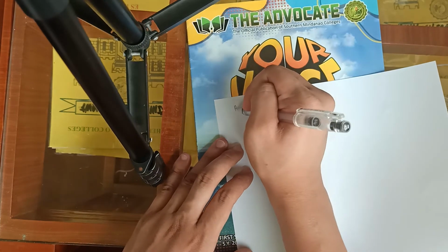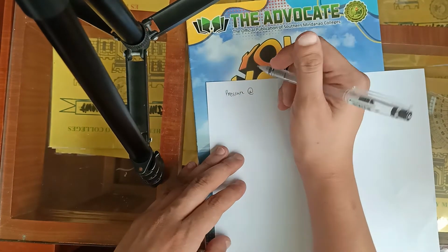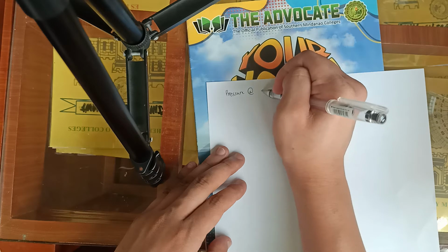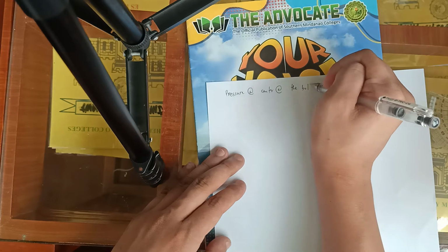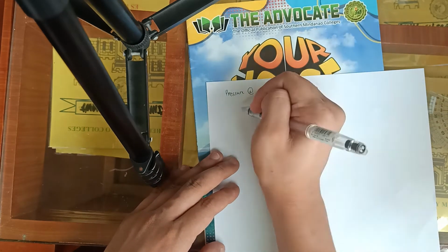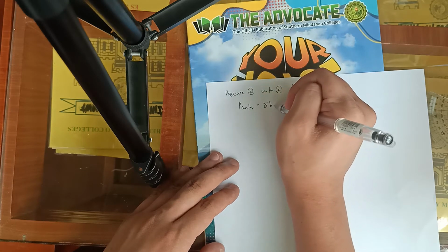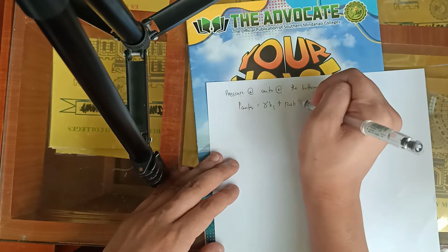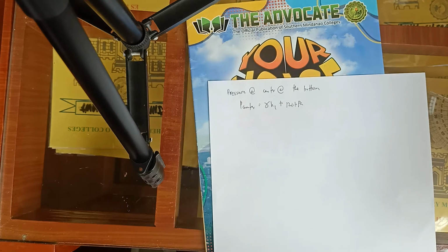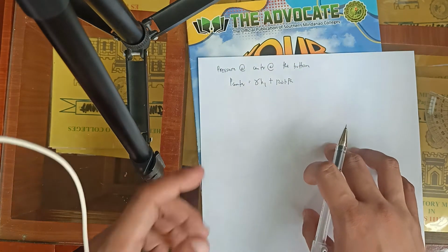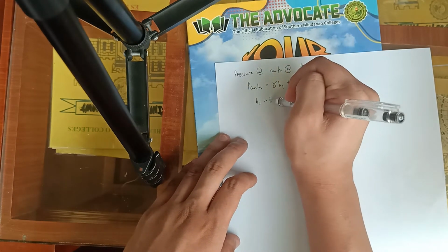And remember that the pressure at the center at the bottom, which is P sub center, equals unit weight times h sub 1 plus 120 kilopascal. It is given that the air inside the vessel is under pressure of 120 kilopascal. So from the equation, h sub 1 equals h minus y sub 1.